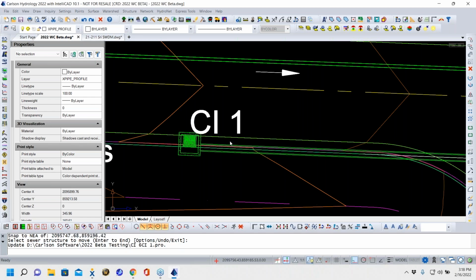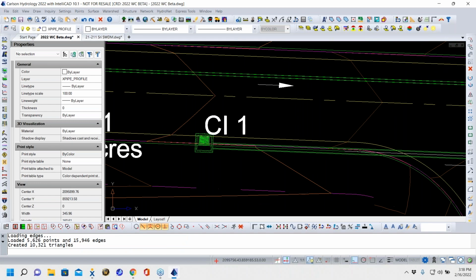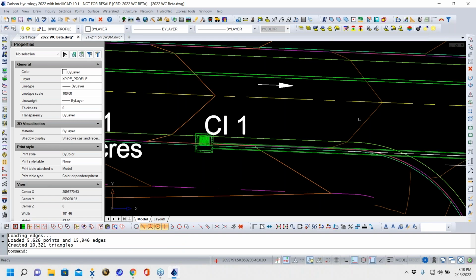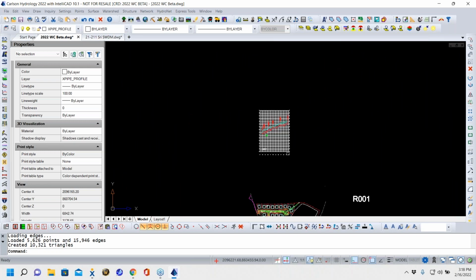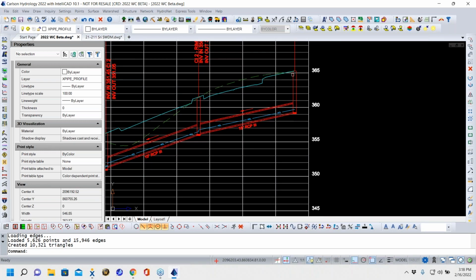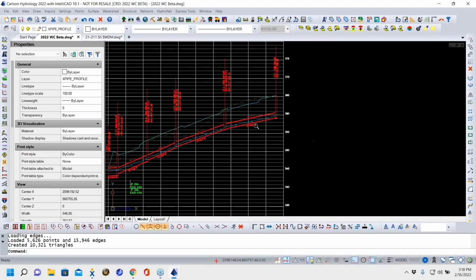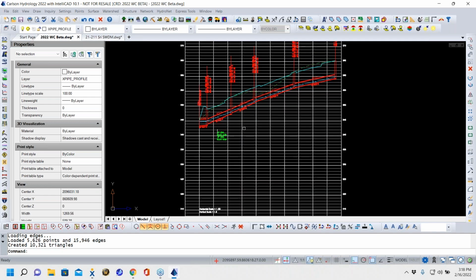Yes to all. Okay. Now what's happening is it's loading the surface model and doing all that kind of mumbo jumbo, but it's also lengthened out and adjusted this. What it does is it will hold this slope and you just move it to where you need it to be. If you get a little too flat, then you can just change it.